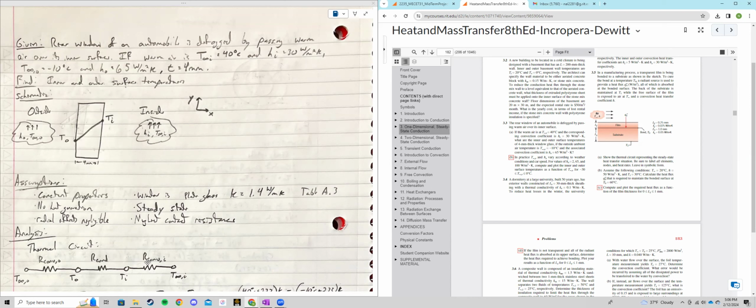And then finally, again, we're going to be hitting some convection with the inside of the vehicle and those corresponding values. So a great way to start this problem is, if you don't know certain temperatures on the in between layers of this question, you could solve for the entire heat flux according to your starting temperatures. So the inside and outside, we can use those two temperatures as the temperature difference and just incorporate the conduction, the convection, the conduction, and then the outside convection again, and we can find what that heat flux is.